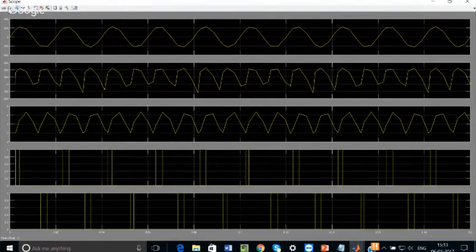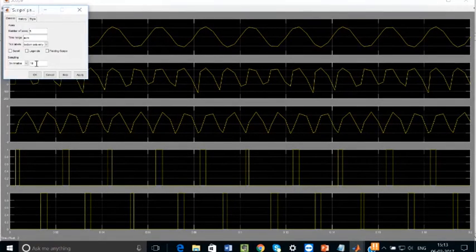Okay, did I change the decimation to 10 or something? Yeah, so that's the thing. That's what I was just wondering, because in this problem, I changed the decimation. In the sense, every 10 samples, it is taking a sample. That's why. So here you can just go and change the decimation to 1. Or 5 or 3 or something you give, it will give more accurate results.